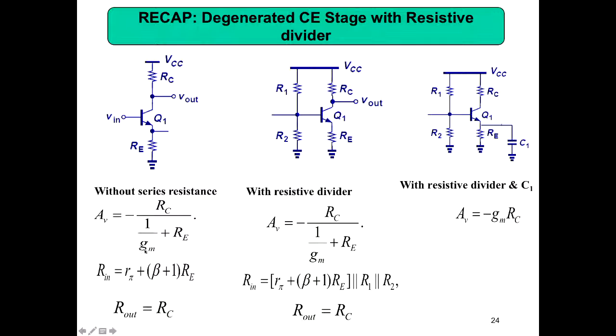For the DC bias, you don't have gm. So all these are for the signal. Then for the signal, when the signal comes here, it will go through this capacitor to the ground, and your DC bias, the emitter current, will go through this RE. Because that DC current is not changing, the impedance is infinity, because capacitor impedance equals 1 by 2 pi FC. For DC, F equals 0, so the impedance equals infinity.